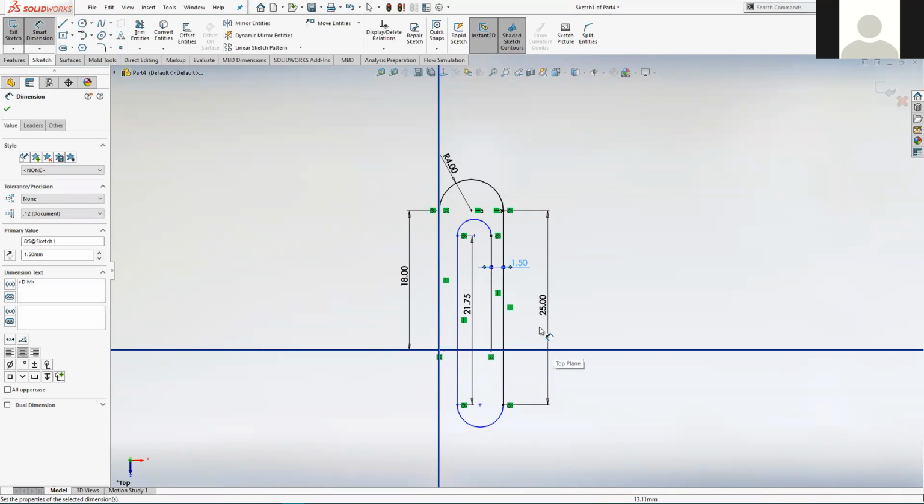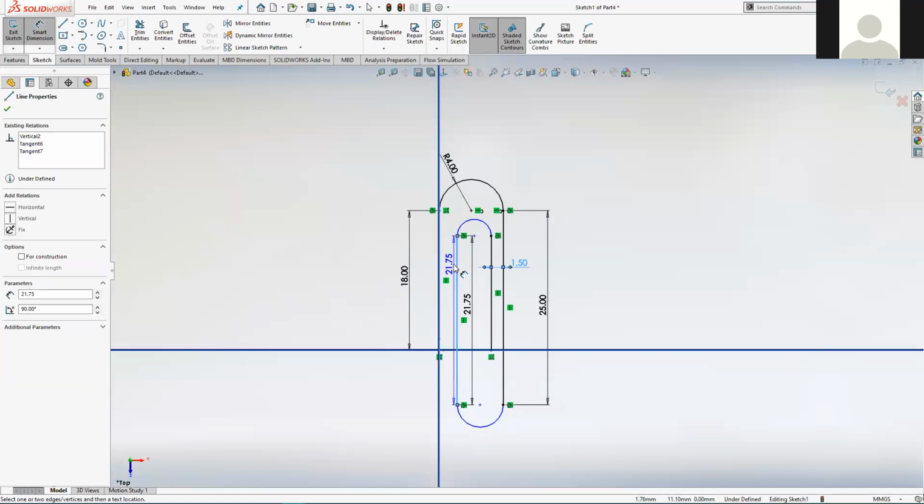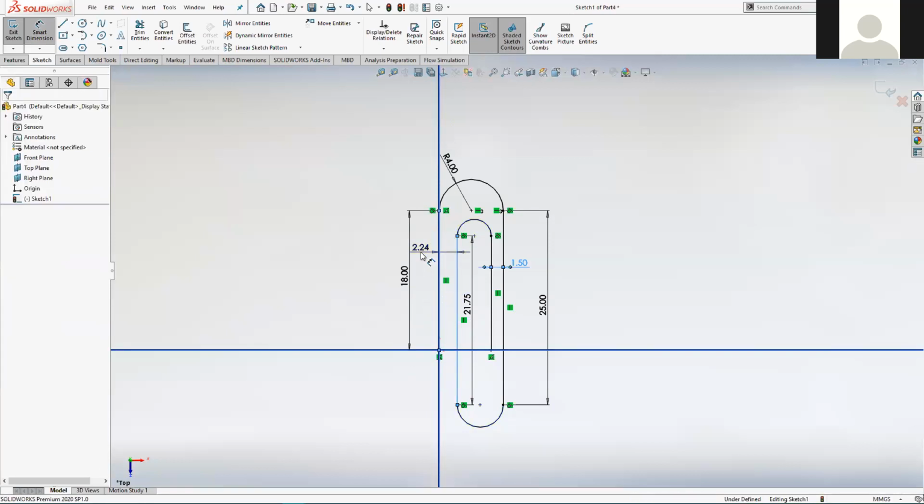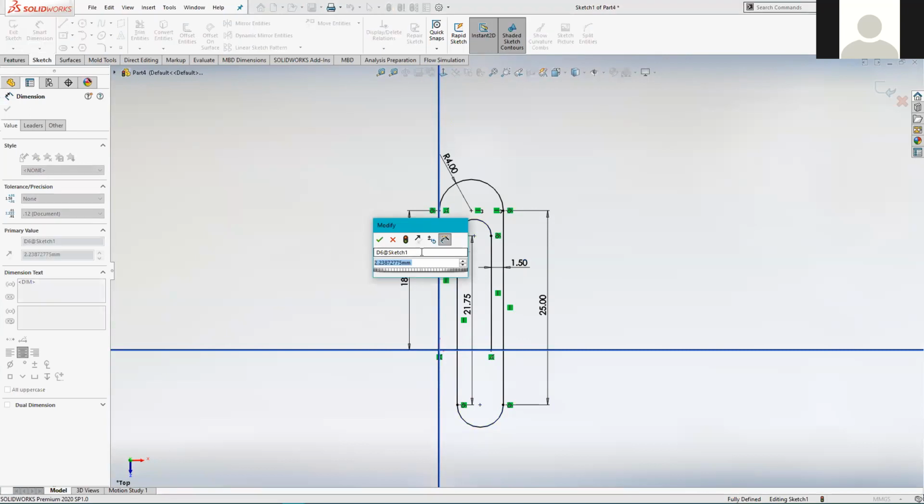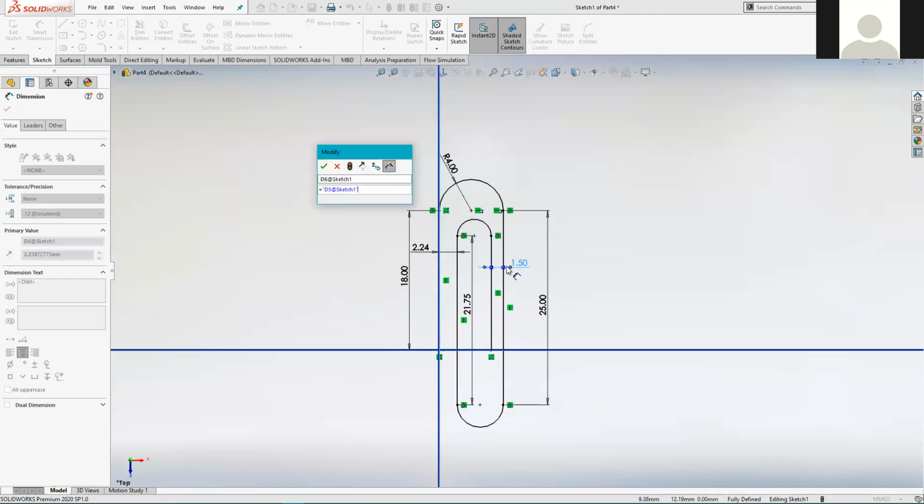like that. And then what we can do here, I'm pretty sure we haven't covered equations yet, but if we click on that leg and go to set the spacing, we want it as 1.5, but rather than just type that in, if we press equals and then click on this 1.5 there, it samples that value.